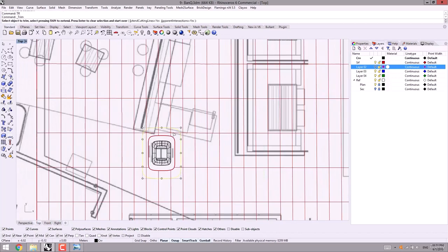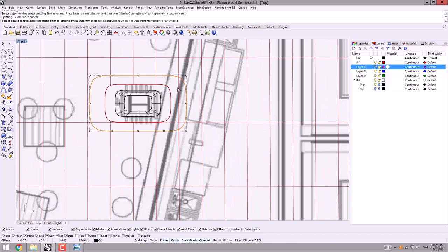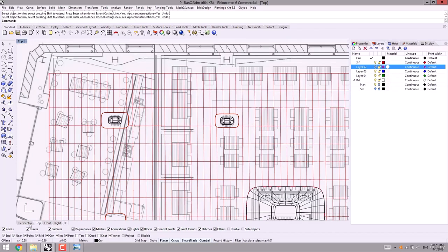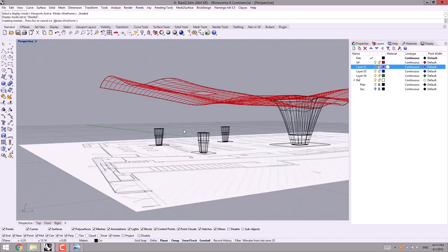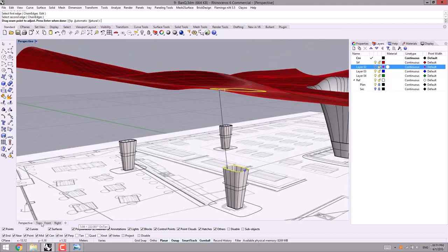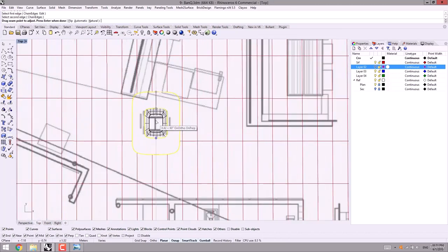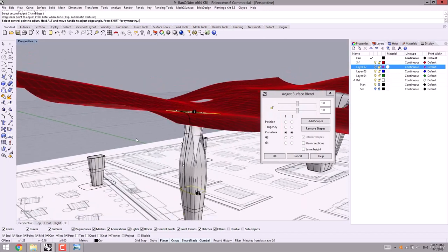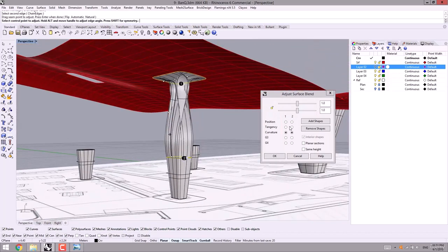Following that, I want to trim the surface by these new curves. Check it out. Since I have changed the size of the curves, I set them to shaded mode, and then I start the blend surface command. Then I choose the surface edges like this. I adjust the seam points, they are well adjusted, and then enter.